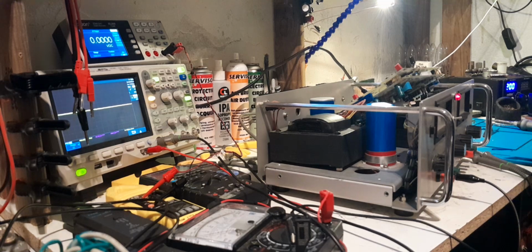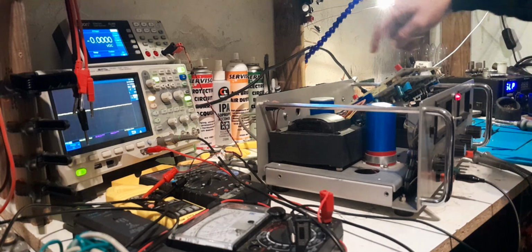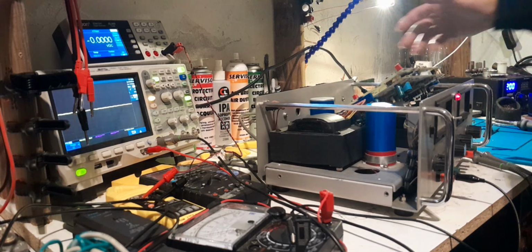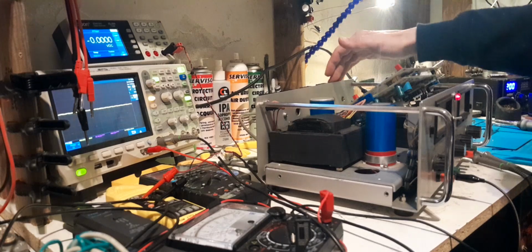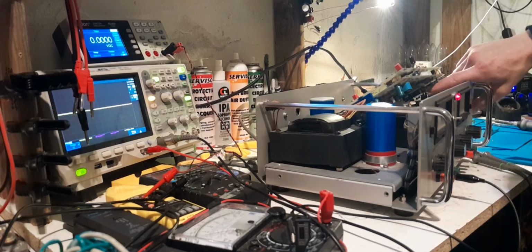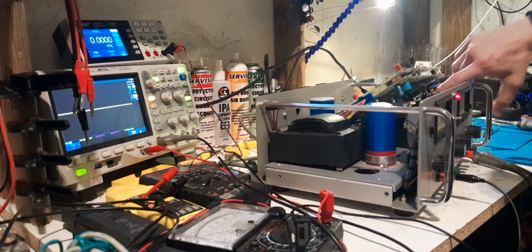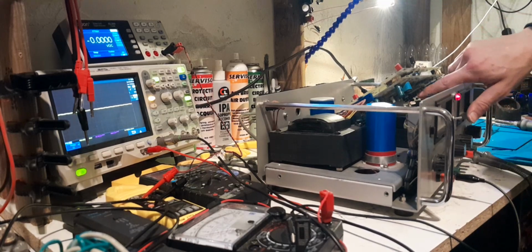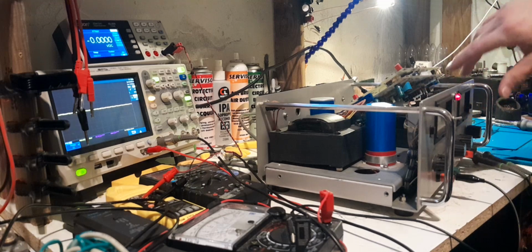I know output drive is usually a concern, but I don't think it is in this case. Although the transistors that drive the output are fairly low gain, like you've got 20-30 hFE on the outputs, and then you've got that driven by another 20-30 hFE transistor, and then that's driven by a smaller transistor, and that's driven by an even smaller transistor.